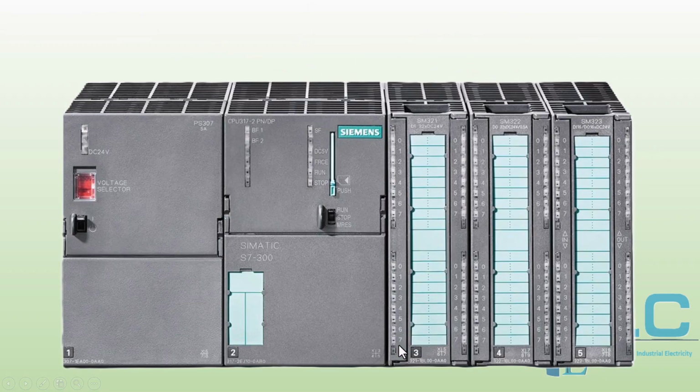In this image, you can see input and output modules connected to the S7-300 PLC. Each module is identified by a unique code that indicates its function and type. Each I/O module in the S7-300 series has a specific identification code. This code provides detailed information about the module, such as its function, type, and whether it's an input or output module. Let's break down the structure of a typical module code.